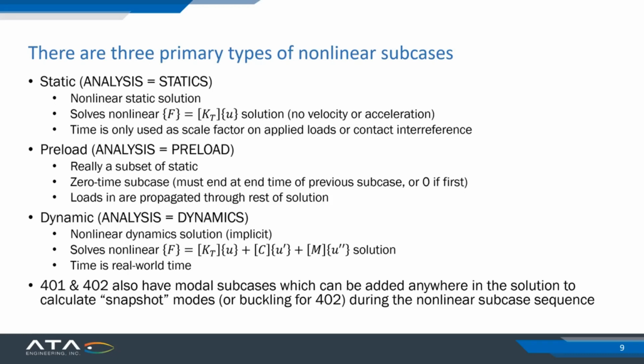The time that you're using in that nonlinear statics solution is simply a scale factor that gets applied to your loads that don't have a time scale on them. So if you are applying a 10-pound force in a nonlinear static solution, it will by default ramp from 0 to 10 throughout the subcase in which it is applied.